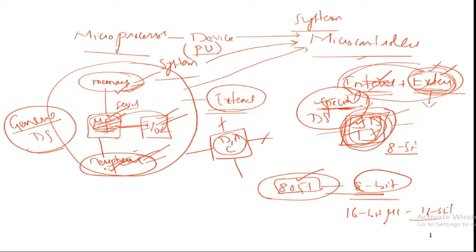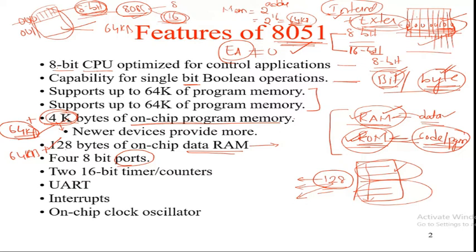So in order to access these particular IO devices, they can be handled in terms of ports. Already we know the terminology, the port in the 8255, as we discussed in the microprocessor interfacing. There we studied that the port is nothing but a pin or a device which is used to take data from any external device and send it out to any device.